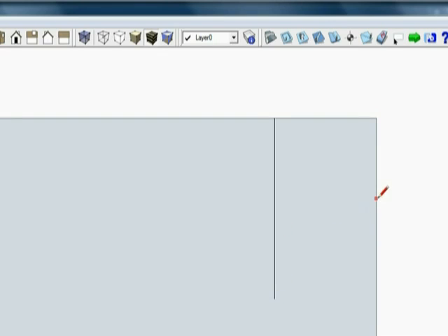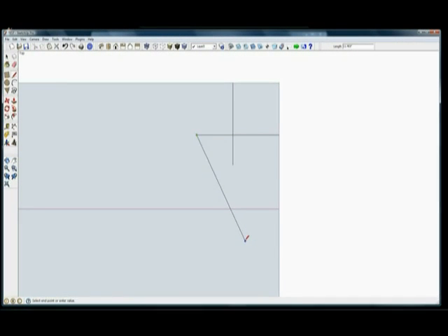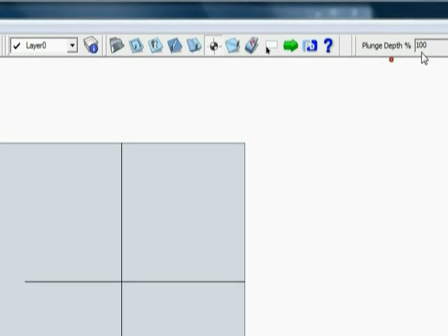Okay, now maybe I want to come over here and we'll draw a click. I'm just tracing the line until I hit 5 inches. And draw here. Maybe I wanted a hole to be drilled in this piece of material right here. Very cool. I can come over here and grab the center line tool, and it has a depth plunge default value of 100%.